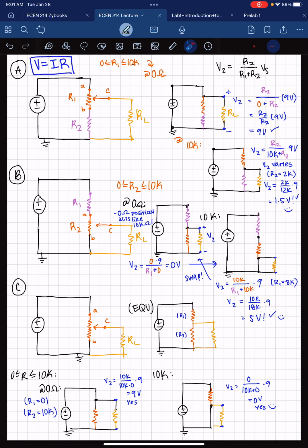So it would be like coming out here, there would be one resistor, and then there'd be this parallel load thing going on. And I did the calculations. I got 1.5 volts, so it's correct and everything. And again, that just varies depending on your value for R2, because the current will vary if you make this bigger or smaller.